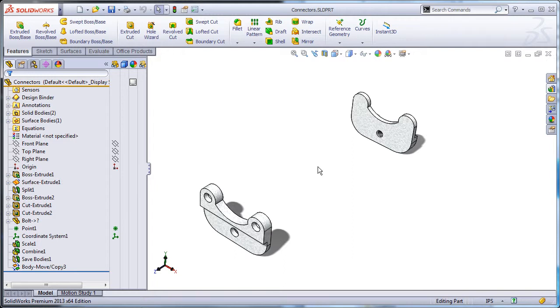When I want to create a new roller coaster segment, I will open the library part, save a copy, close the library part, and open the copy. If I make changes to the master part, it will affect the next part I try to make from it. The only way to lock this down is to set the folder property read-only or use Enterprise PDM.